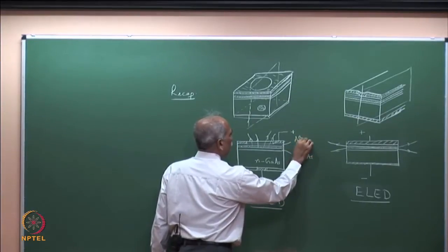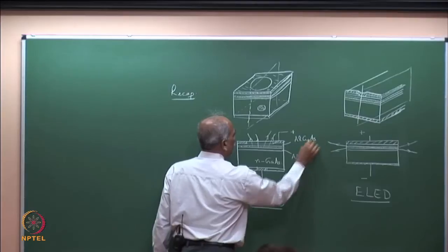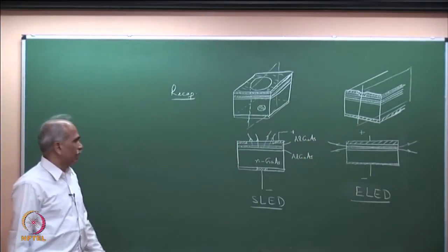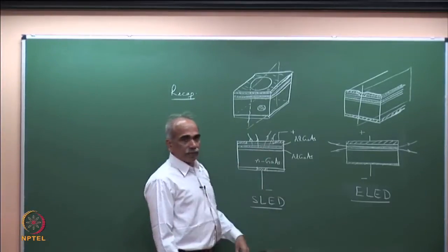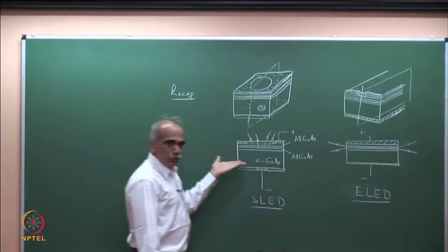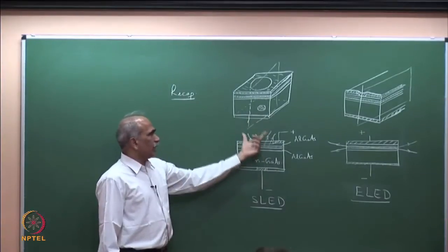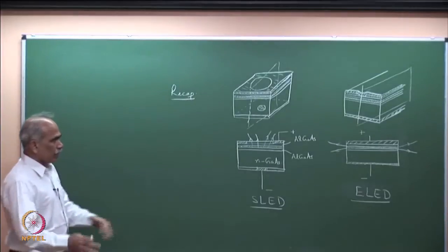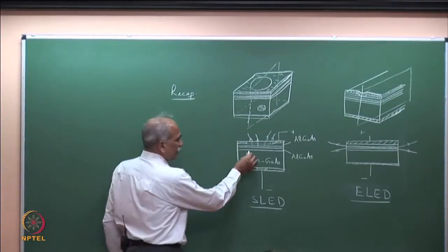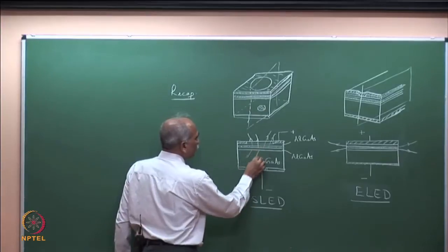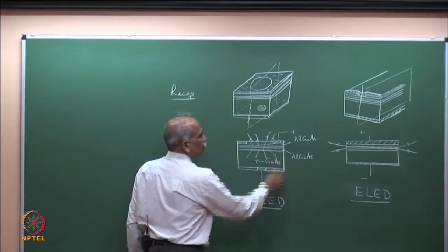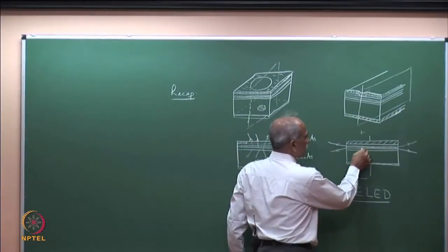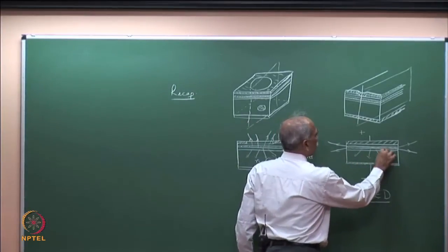and an active layer in between, which could be of a different composition, aluminum gallium arsenide or gallium arsenide. So, that is the active layer. The structures look almost similar, and there is a window here and the light comes upwards. There was a question about the light which goes below, that is into the substrate. This is usually lost, it is a waste. In both cases, light that comes down here is a waste.